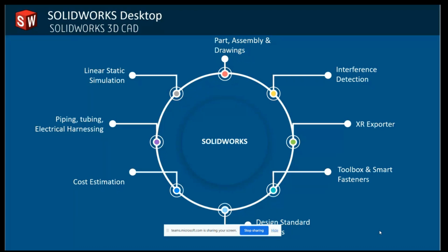SolidWorks Premium includes design tools that build a path of pipes, tubes, or electrical cables for assemblies. Routing creates a special type of subassembly that builds a path of pipes, tubes, or electrical cables between the components, to simplify the design and documentation of piping and tubing for a wide range of systems and applications, including machinery, skid systems, and also processing plant piping.